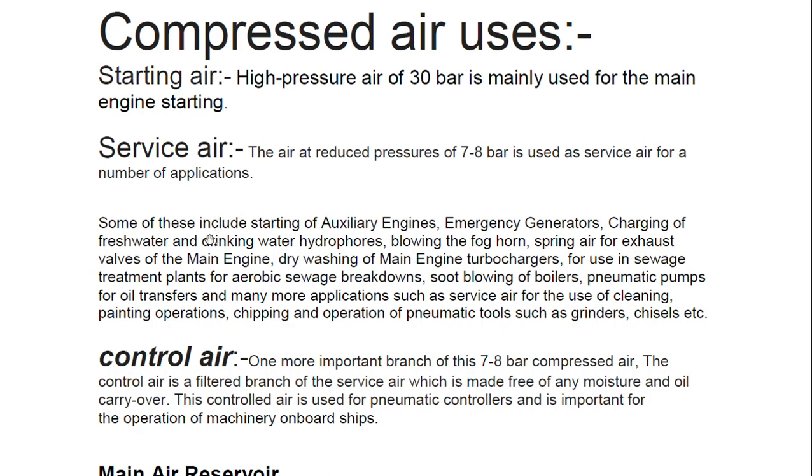So for what purpose do we use service air? As starting air is used for main engine starting, service air is used for the auxiliary engine, which may also go up to 11 bar, the emergency generator, and charging of fresh water and drinking water hydrophore. You see that the hydrophore tank is half filled with water and half filled with air, mostly 70%. Likewise, blowing the foghorn, spring air for exhaust valves of the main engine, dry washing of the main engine turbocharger, and use in the sewage treatment plant for aerobic sewage breakdown in the STP.